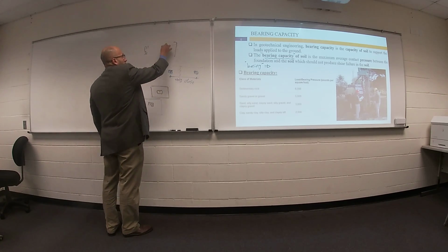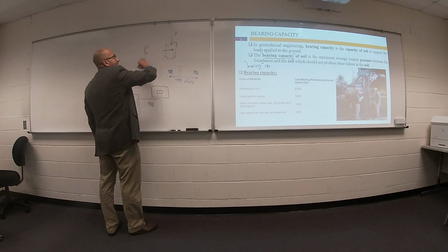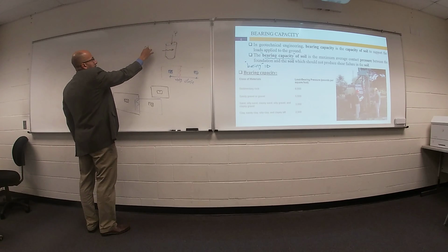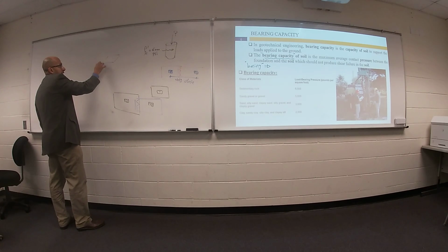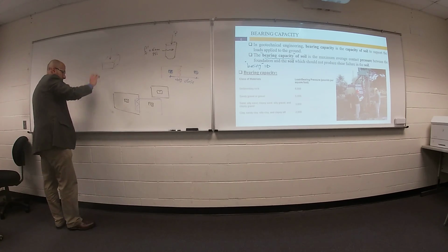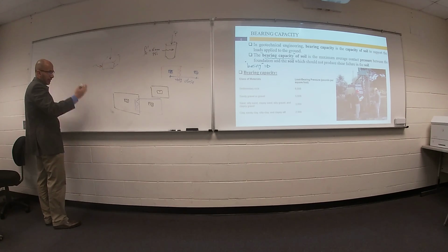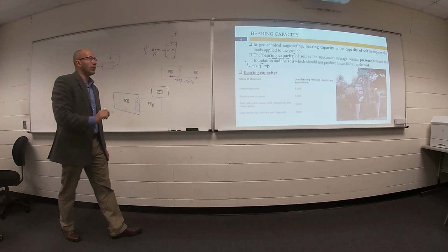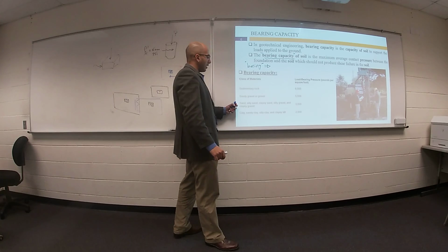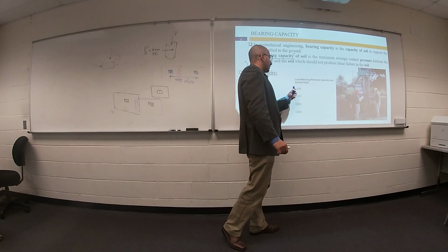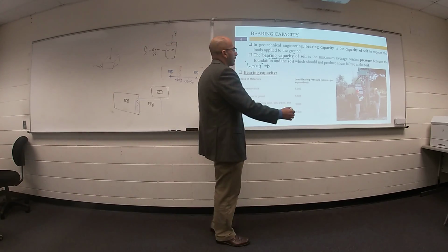Last time you saw, if you have a cylinder and apply compressive force, this concrete can support stress until maybe 6,000 psi. Okay, I have soil and I apply compression force. Can you tell me the compressive strength of this soil? We call it bearing capacity. Based on the type of your soil, I can expect the bearing capacity in psi, or pounds per square feet.